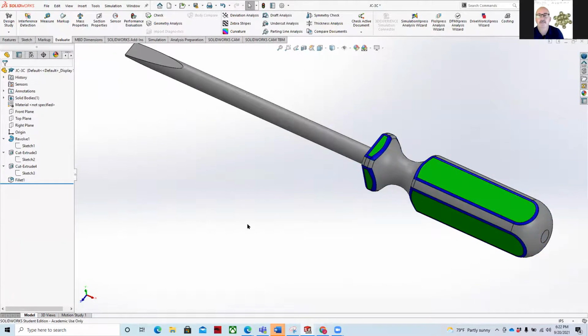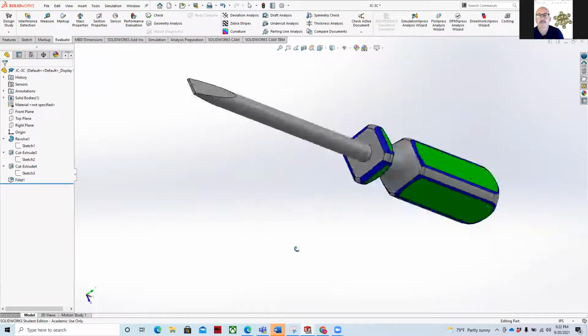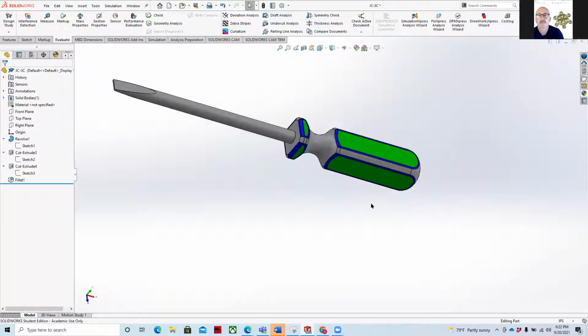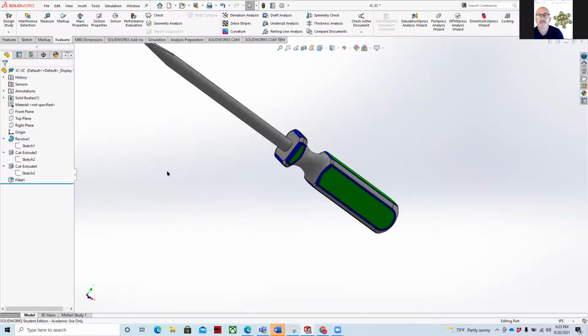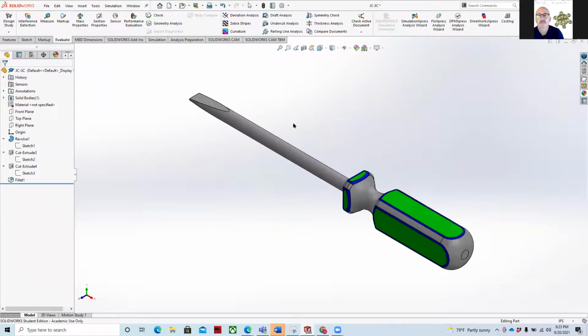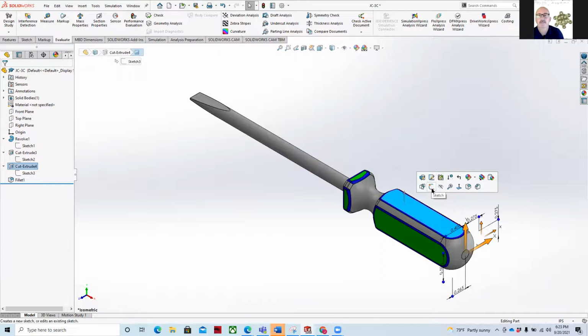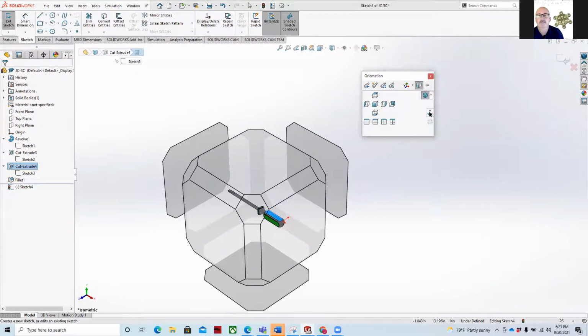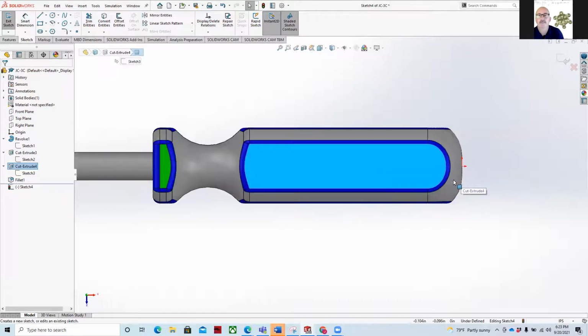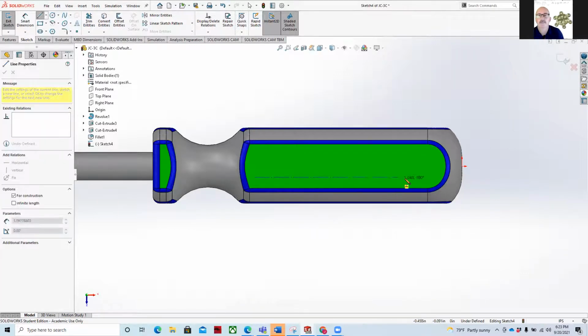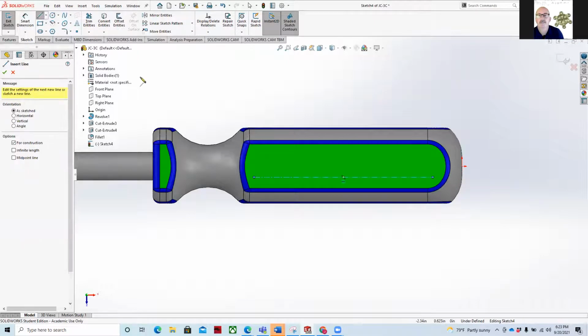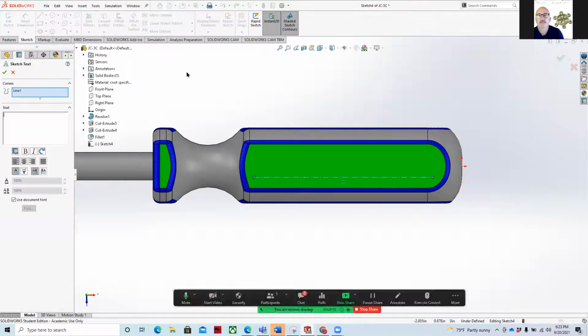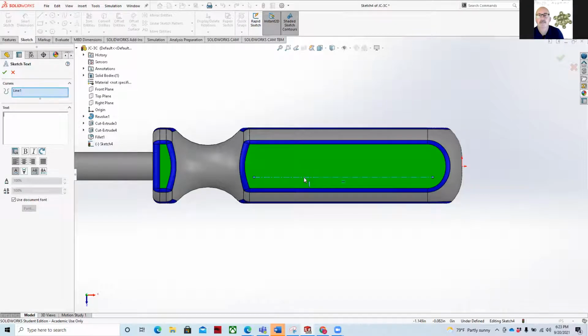If you want to put your name on it, and you're 3D printing this and everybody else is 3D printing it, what we would do is let's get an isometric view. I would choose a plane, and then start a sketch on that. I hit the space bar and go normal 2. You don't have to go normal 2, but you can. Then I would make a center line for where the text is going to be. Once I have that, I'll green check mark that, and go to the A here, the text tool. And then it knows that's the line I want to put that on.